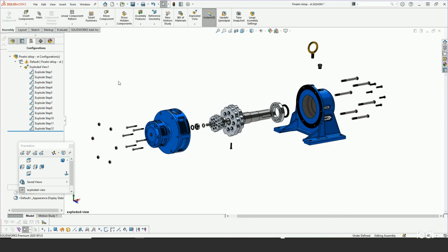So that's my methodology, in that it's very cool because exploded views are parametric, and you can treat them that way by the way that you select and group components for your explode steps. And then once everything is kind of logically exploded, you can start to move things so that they're out of the way of other parts. And that's what I've done with this last part of this video, is to show you how you can do that. And it's a very good methodology. It's worked for me. I hope it works for you.